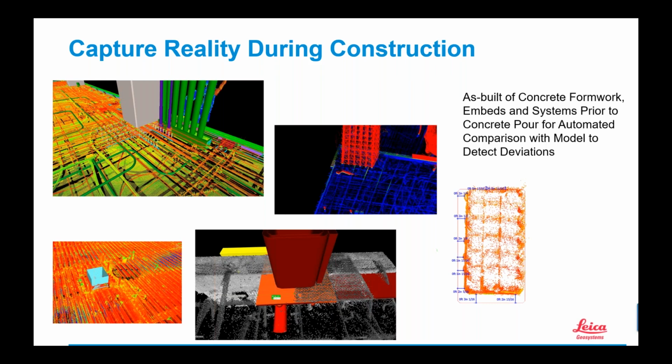All right. The other thing I want to mention here is, there's a big buzzword, digital twin. Laser scanning is not a digital twin. Laser scanning is a means and methods to start establishing a digital twin. I can go out, I can laser scan, I can come back to the office, I can accurately 3D model that building and put those assets in my model. For instance, all the conduit. If you notice on the top left picture, it looks like a conduit duct bank coming up. I know where that's at.